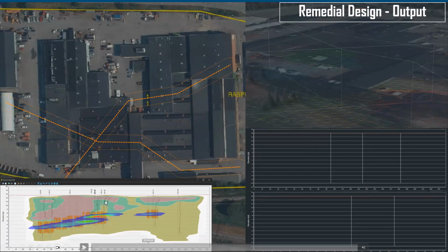But by following the range of the EC, you can get a general idea of the type of lithology. So in this case, we have been able to get a proper picture, because we knew that at this site we had soft clays in the upper formation, and then we knew that the water table would start at deeper and deeper levels as you moved from east to west.